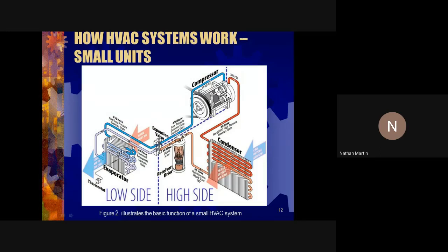All right, so here we have our evaporator. This is under your dashboard, and you will find your thermostat device under your dashboard as well. What your thermostat device does is cause your compressor to turn on and off based on the temperature inside the car.